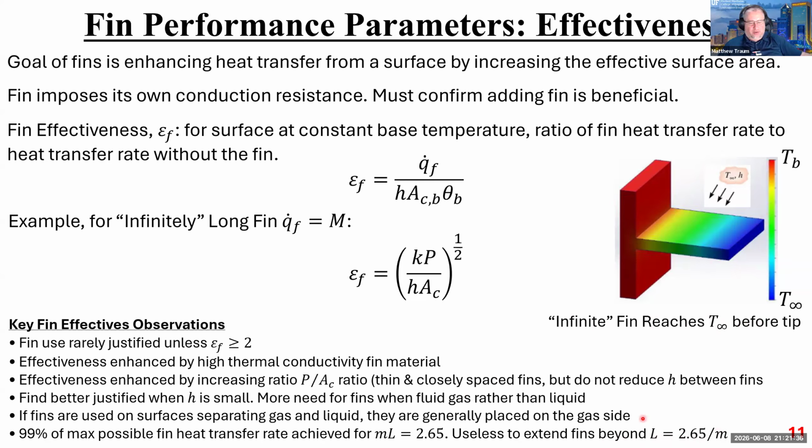And so this is a good rule of thumb for fin design, right? Just don't make your fins any longer than this because there's no point in adding any material after that length. Okay. What's next?